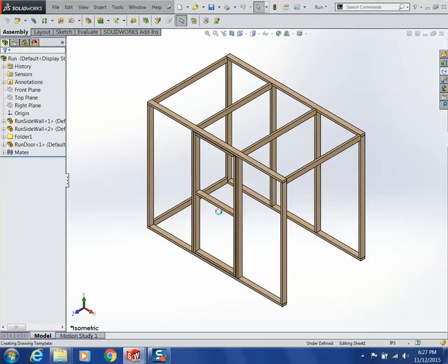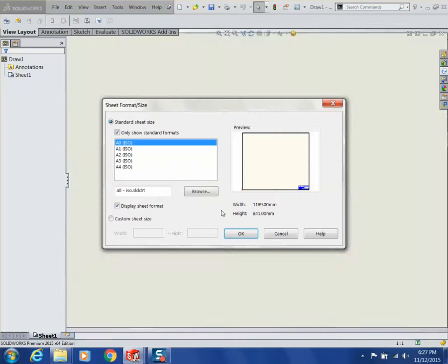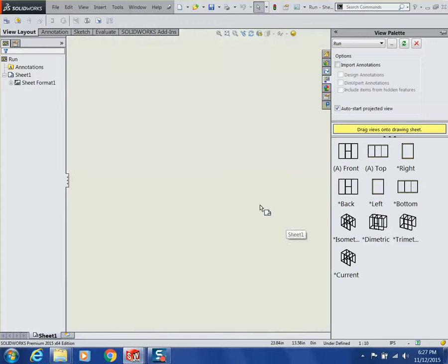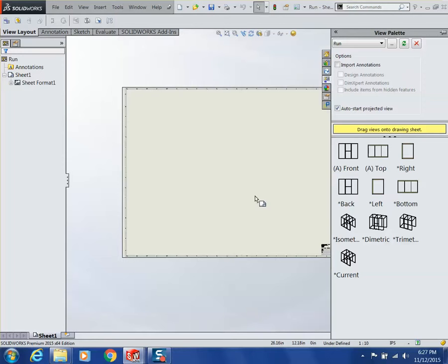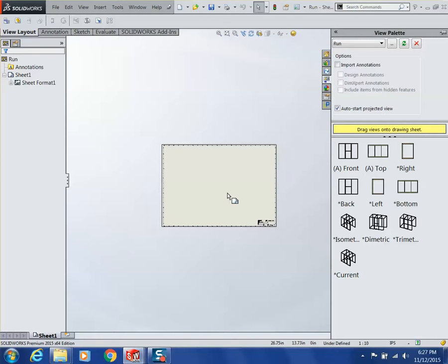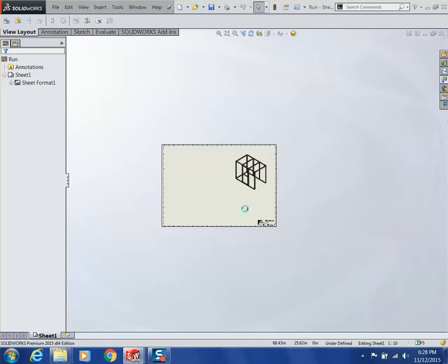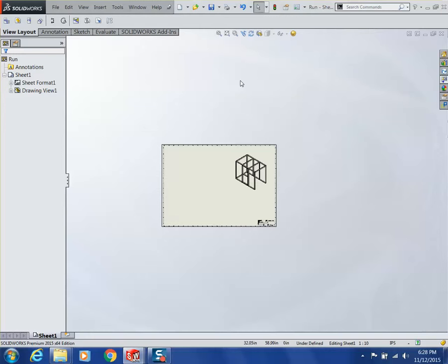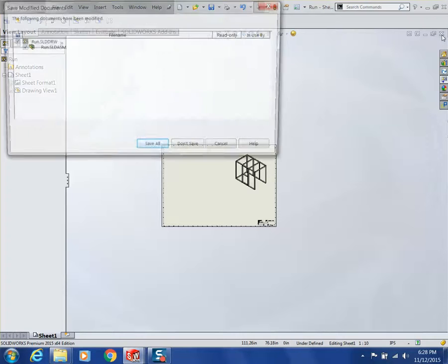And because this is a fresh install, it's going to think about it. So when I said make a drawing from part, now I'm going to pick template. I don't have any pre-populated in here. If you have pre-populated views, they come in automatically. If you don't, it comes in assuming you're going to run it this way, and now you can drag and drop your views out of here the way you normally would. So that make drawing from part or assembly is beneficial there.